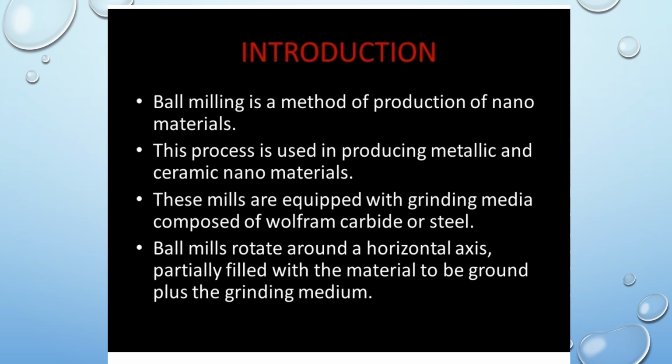Conventional methods for particle size reduction include milling, grinding, jet milling, crushing, etc. Ball milling is an efficient tool for grinding materials into fine powders. The ball mill is generally used to grind different kinds of materials and to obtain ultra-fine powders. It is widely used in ceramics and chemical industries. There are two types of grinding or ball milling methods available, namely the dry and wet process methods.